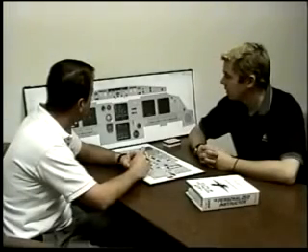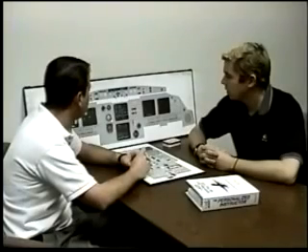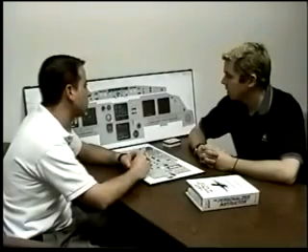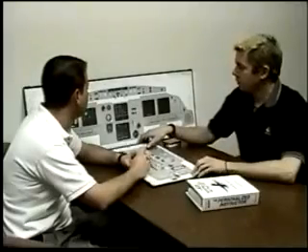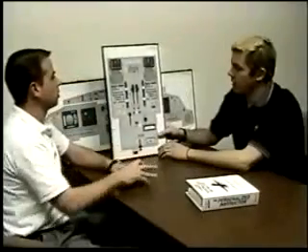Let's assume that the green hydraulic system failed, the landing gear is up. How can we extend the gear? And is this an ECAM procedure or a non-ECAM? This is a non-ECAM procedure. You'll get a note in the ECAM on the hydraulic failure to say you'll have to manually extend the gear, but the procedure itself is in the irregular section. To do that, basically you're going to have to crank the gear down. It's 3 turns and it's a pretty easy one. I don't even know what each turn does, I just know that I have to crank it 3 times.